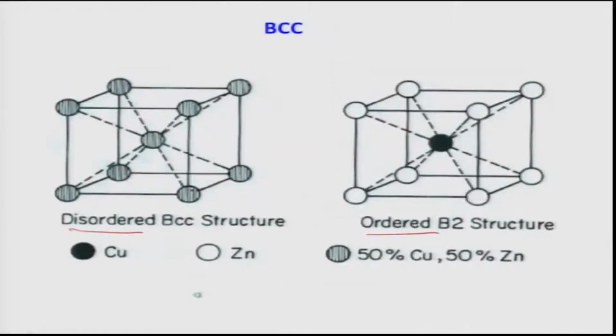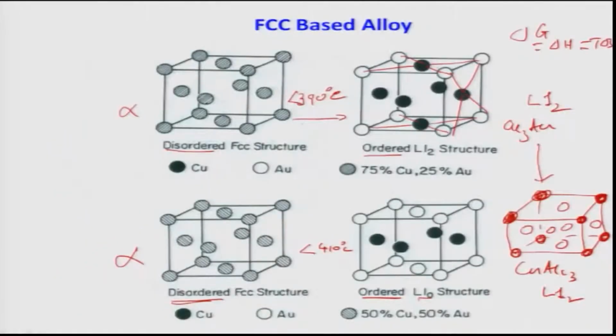Which are the 110 planes here? Let us go back to the crystal structure. You see, this is one of the 110 planes. So if I draw a body-centered diagonal, which is the 111 direction, half 111 displacement means one atom going from here to the central atom, which is basically half <111> here.